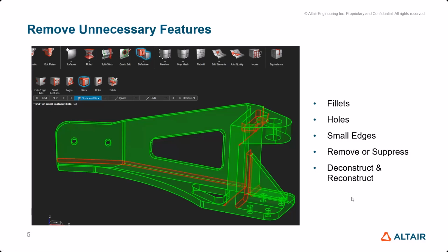So you delete the solid, keep the surfaces, then go in and delete the fillet surfaces or whatever surfaces you're trying to defeature, close back up the solids in those gaps with straight edges. And then once you have a fully enclosed set of surfaces again, you can recreate your solid and move on from there.